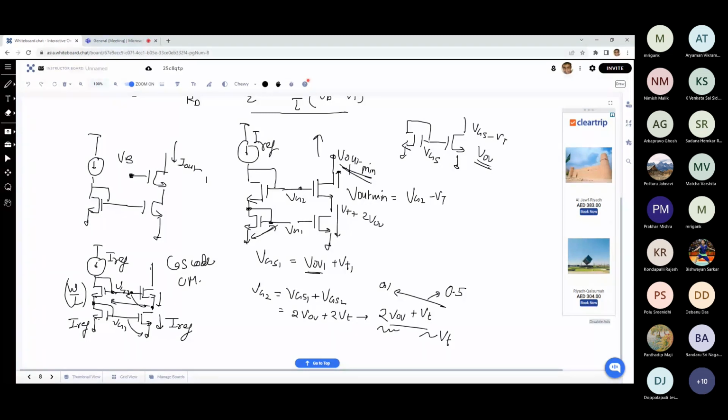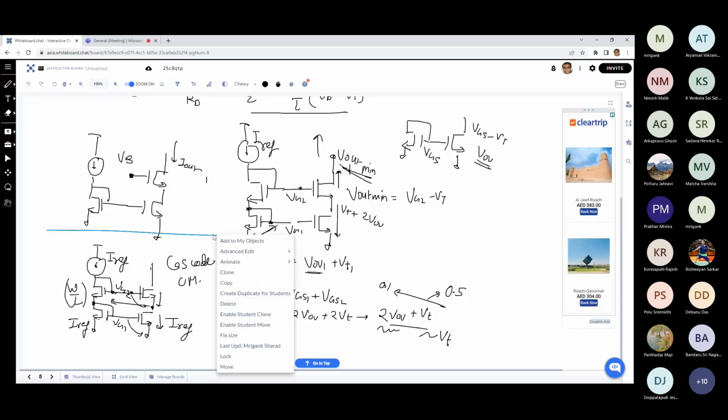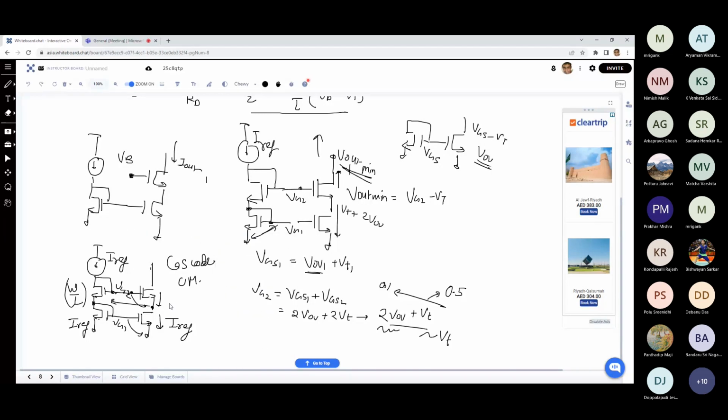We will discuss that in the differential amplifier case. But V overdrive, at least we can reduce. So in this case, you can see that definitely you are adding a VT. So you are eating up some headroom, or basically you are demanding more headroom for the current source to operate, which is kind of a disadvantage. In order to mitigate the disadvantage, we have a slightly modified configuration which people use wherever there is a need for higher headroom.